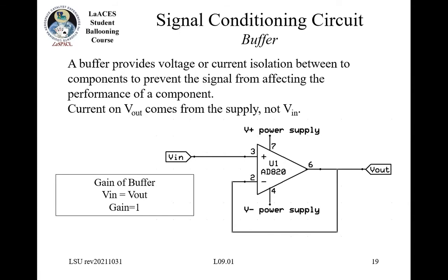So the simplest version of one of these things is an op amp where the gain is just 1. The output signal matches the input signal. That's fairly simple. You just connect the output back to the inverting input, and your actual signal goes into the positive input. And what you'll get is that V in equals V out. Now, you may then wonder, well, what good is that? Who cares? I haven't changed the signal.